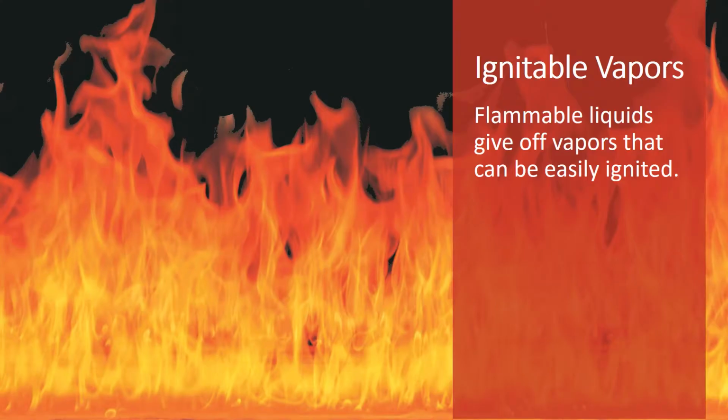Flammable liquids give off ignitable vapors. Therefore, wherever flammables are located, associates must be aware of ignition sources. Even static electricity can ignite a flammable vapor. In addition, nearly all flammable liquid vapors are heavier than air and will accumulate when they escape from a container.